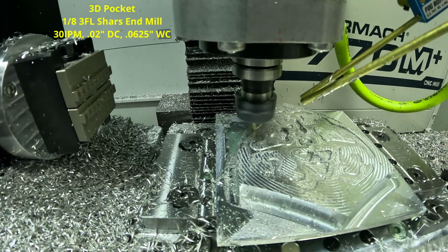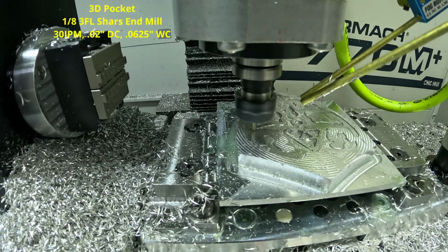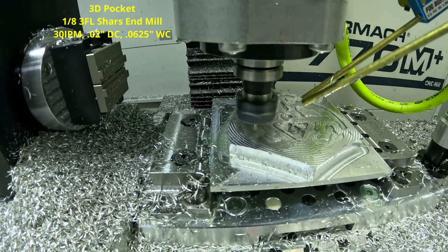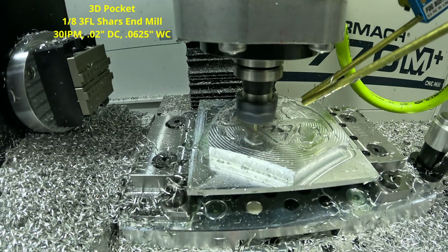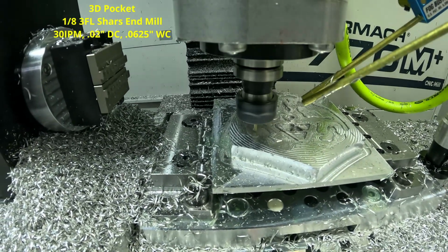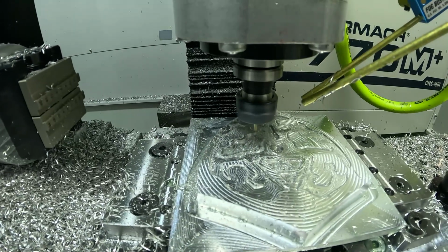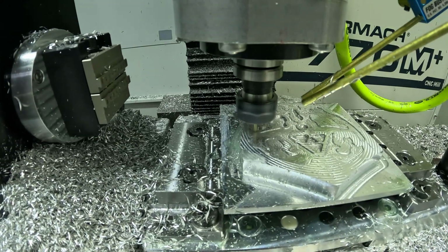All right, so here we are with the 3D pocket. We're using a 1/8 3-flute Harvey mill, 30 inches per minute, 20 thou depth of cut, and 50% of the diameter of the tool for our width of cut. Again, this is where most of the machining occurs. It is the longest toolpath, so we will skip through most of the machining here, but you can see the inside of the Hylian shield start to take shape. And again, this is where all the complex geometry is. The surface finish in there also looks beautiful, but it's not as critical since we will be filling it with epoxy. So what we'll do now is transition into our chamfers, and that will finish Op1.